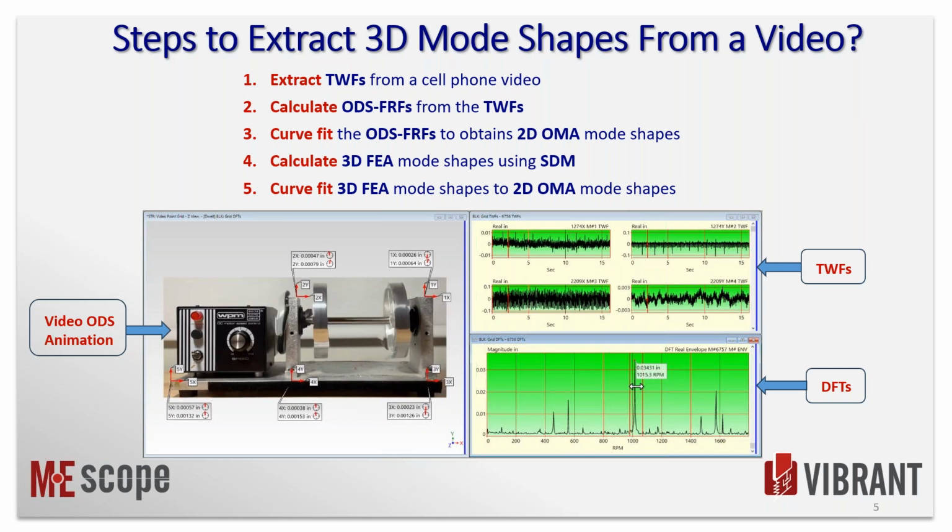So again, cell phones are much lower frequency. We're talking about bigger structures, but if you're looking for mode shapes or resonances at 5 kilohertz, accelerometers are probably better and easier to use. Even there, you're getting up to the bandwidth limitation of the accelerometers.